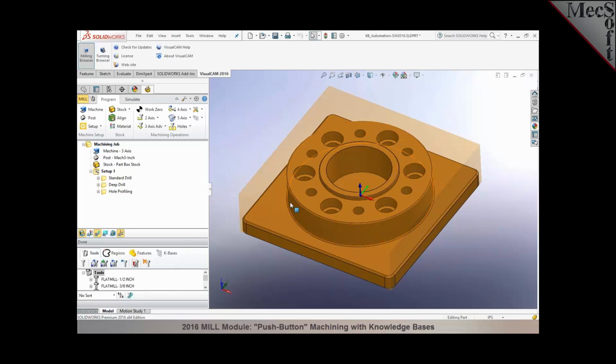Now, the way we would save and load knowledge bases is very similar to how we saw in standalone Visual CAD/CAM and in RhinoCam, but for the rules, it works slightly differently inside of SOLIDWORKS, because in SOLIDWORKS we do not use layers. There's no layer concept, so we would have to reference them using some sketch geometries. The way we would do it is, in SOLIDWORKS, you would have to create some extra sketches around each of these features that you're trying to select or automate the selection process for.